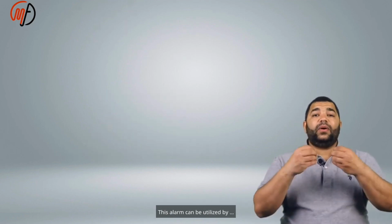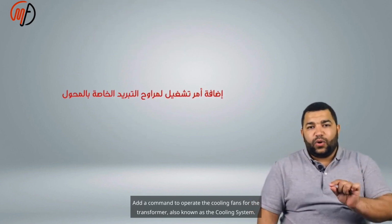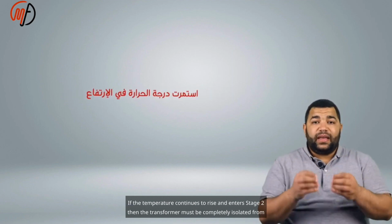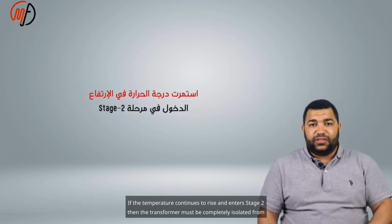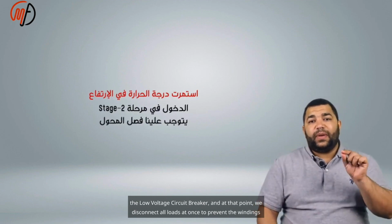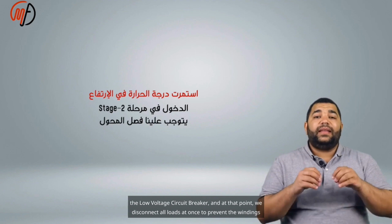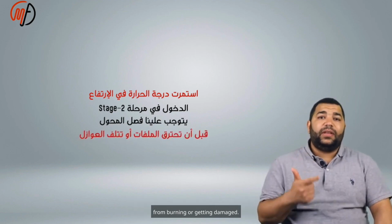This alarm can be utilized by adding a command to operate the cooling fans for the transformer, also known as the cooling system. If the temperature continues to rise and enters stage 2, then the transformer must be completely isolated from the low voltage circuit breaker, and at that point we disconnect all loads at once to prevent the windings from burning or getting damaged.